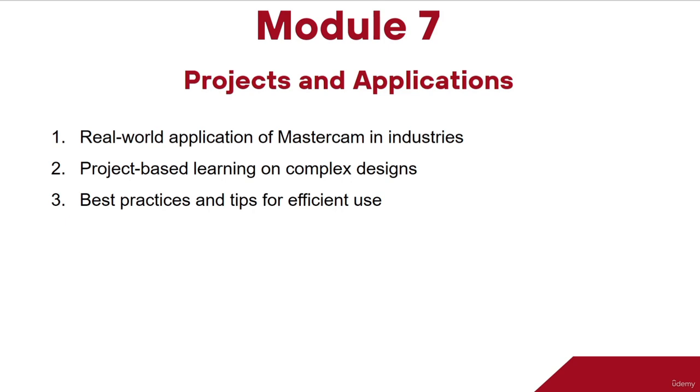We discussed the 2D face operation, pocket operation, contour operation, and drilling operation, all in the 2D operations. After completing the 2D operations, we discussed how we can create 3D models in Mastercam. We used the block command, the loft command, and the sweep command. We discussed how we can create 3D models using 2D wireframe geometries. We discussed the extrude command, and we used the pattern command and the copy command in Mastercam.